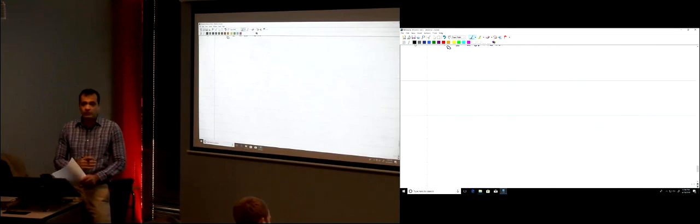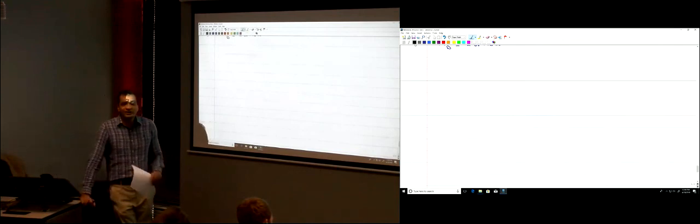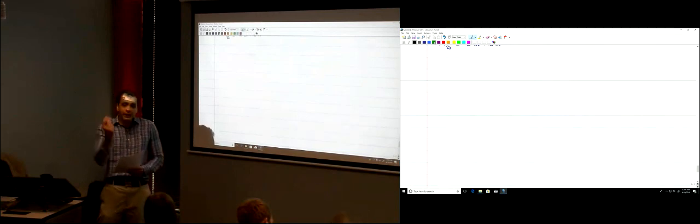It's helpful to draw the influence line for any beam, but it's a qualitative method, okay? That means it will not give you the height of the influence line, but it will give you the shape of the influence line. So you will not be able to use it to find the internal forces or the reactions using the method that we found, but you're going to be able to use this influence line to find the location of the load that maximizes that function. You understand what I'm saying here?